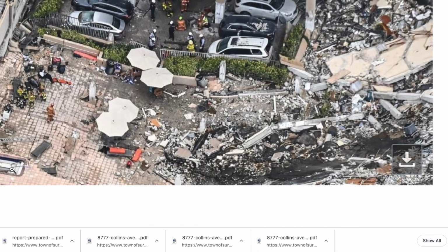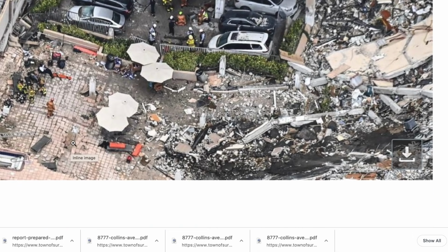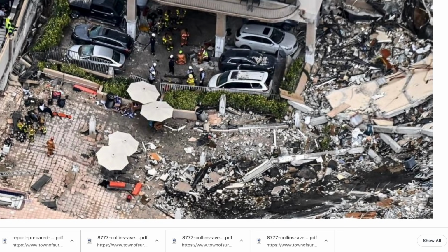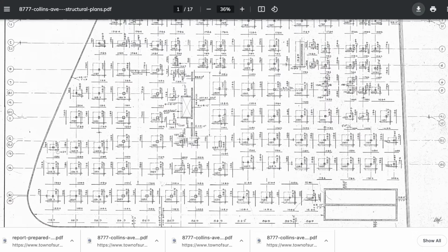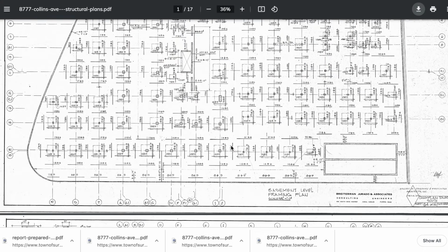So you get some heavy braking there, etc. You can exceed your dead loads via a shock load of the vehicle slamming on brakes. Jackhammering that surface can be an issue.